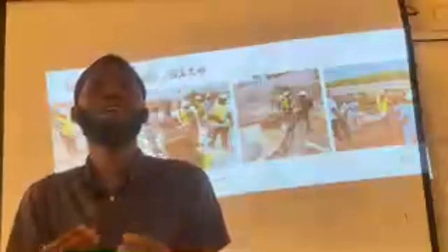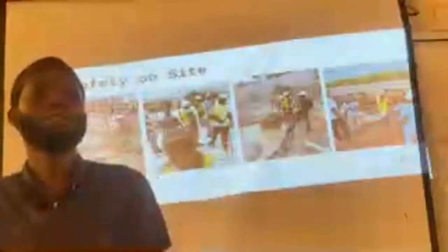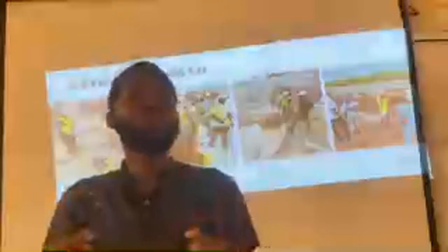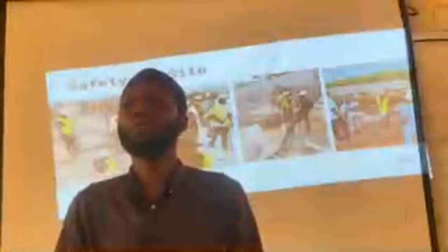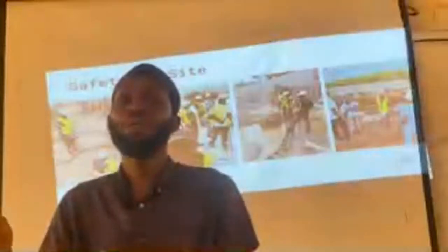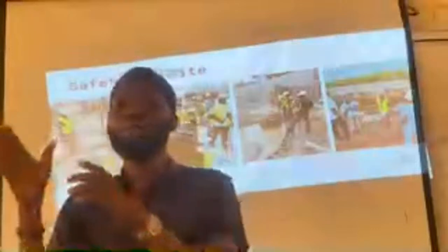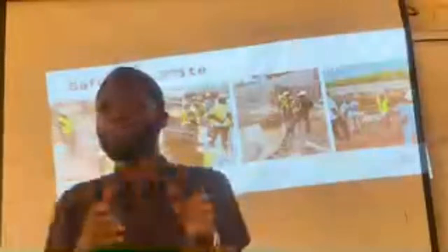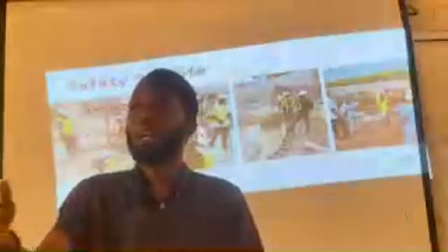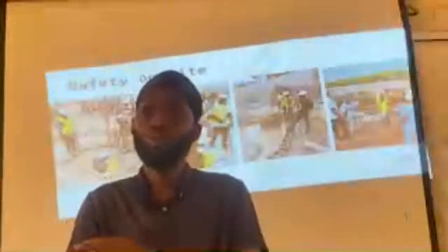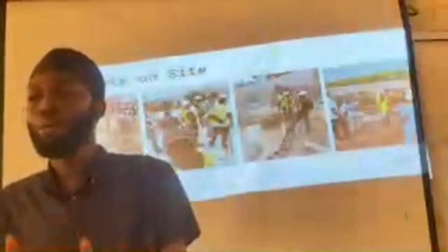But when you cover more than 50% of the structural elements in the building, probably 60, 75, 80%, that's good to an extent. Even if you have access to those particular apartments, you might not be able to test all the structural elements because some of them might be embedded in the wall. On demarcations, there might be some structural elements located. So you won't be able to test those. Probably on the first floor, second floor, where there is no veranda or front porch. Everything like that will be stated in the report. That's the compilation of everything you observed on the site.